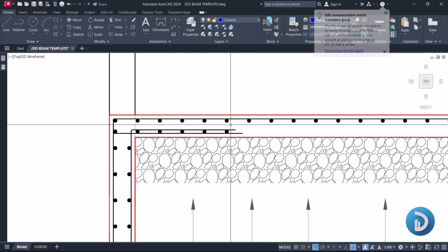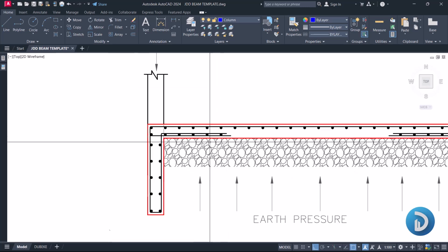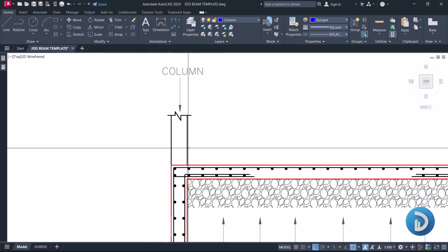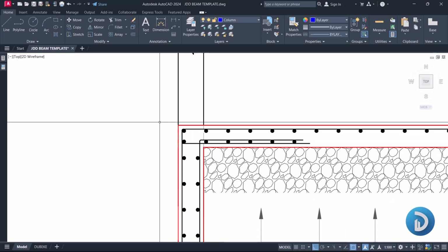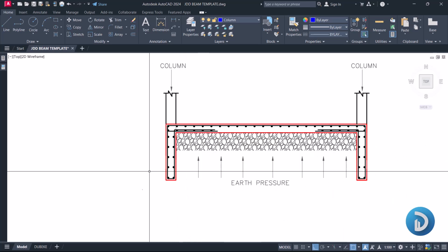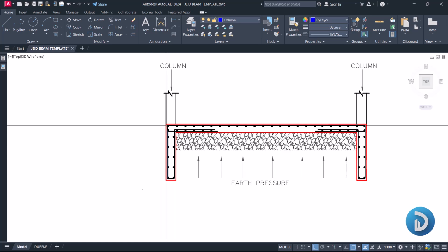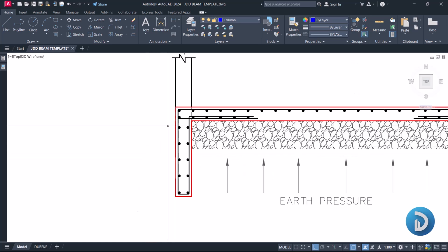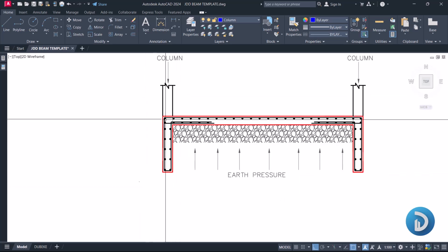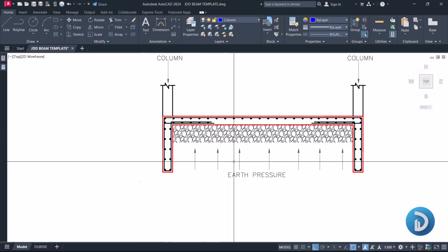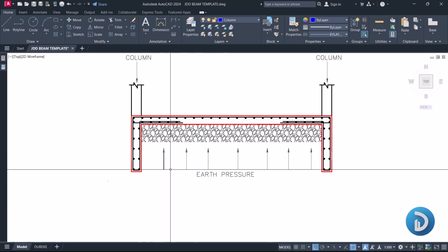Because if we are to leave our slab of 250 millimeter to counter the punching stress that is coming from our column, then we will definitely have our slab failing in punching. So our beams are here not just to create a rigid frame for our slabs, but in turn eliminate punching due to its thickness.